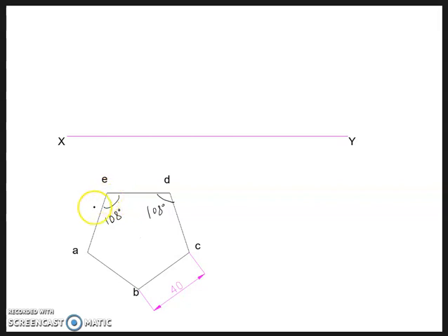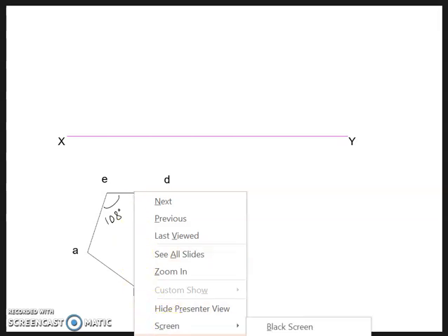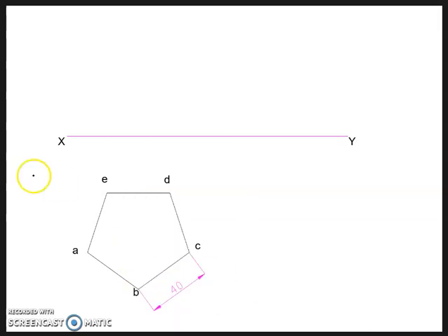Okay. So now to construct the slant edge, you first need to locate the apex. And I have already explained how to find the apex. To find the apex, we drop a perpendicular from any two adjacent corners to the opposite sides.